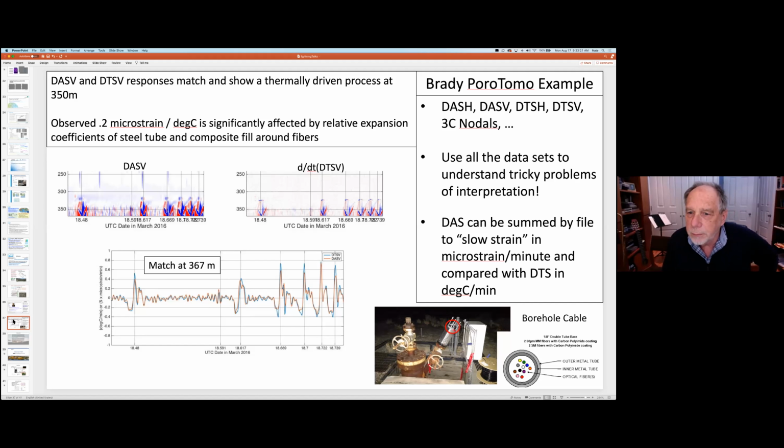And it's a bit puzzling when you consider that the thermal scaling coefficient that makes this match is about 1/100th of what you would predict if you considered only glass and steel. Evidently, the goo in this loose tube cable has a significantly smaller thermal expansion coefficient than either of those other 2 things. The events here are part of a repeating heat exchange process that persisted throughout the survey period and was still evident when Chris Kratt and Scott Tyler from UNL repeated the temperature survey in 2018.